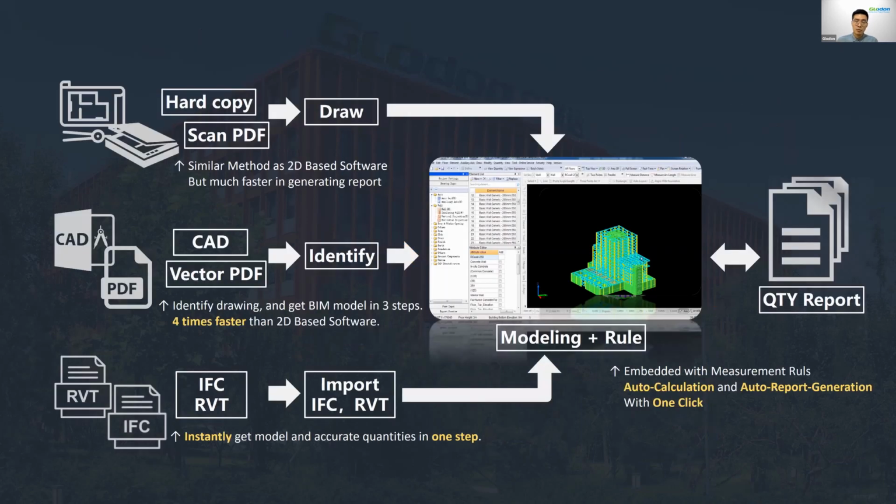And this is how exactly it works. You might think about, if I don't receive 3D models, how do I do my work in BIM method as a QS? This is the thing. No matter what types of drawing information you have, all the way to 3D, you can always do your work in 3D method. So, for example, when you receive a hard copy or scanned PDF, you use the trace function or the draw method to build the model. It's actually something similar to what you do in the more traditional method.